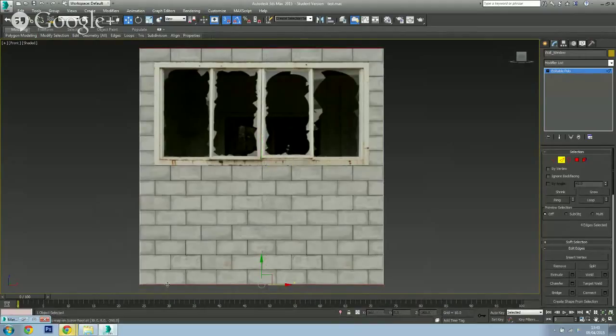And what that's done is it's selected each of the lines on the top, one at the top and one at the bottom, and highlighted them red. So then I want to just select the connect tool over here. So the little settings box, I'm going to hit that, and that adds me in a connect straight through the middle. What I then want to do is make sure that I have more than one. So I actually want 2 connects, and then I can kind of mess around with these tools here just to make sure that it reaches where I want it to.